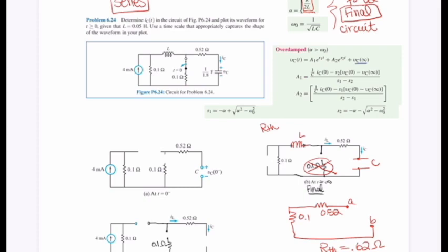So in the initial zero minus, the switch is still closed, and so this circuit will not be valid. You want to redraw that circuit with the switch, so this will be open, and this will be a wire. And then you want to find the current.